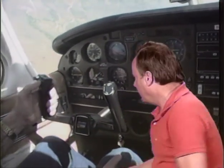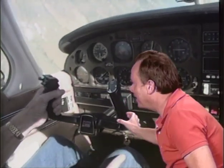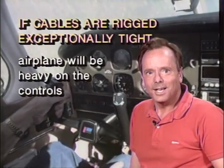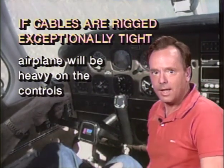Now, if the travel of an airplane's controls is correct, but the control cables are rigged exceptionally tight, the airplane will be heavy on the controls. So if you find the airplane is heavy on the controls, it might mean that they are rigged exceptionally tight, and that causes the airplane to be heavy on the controls.